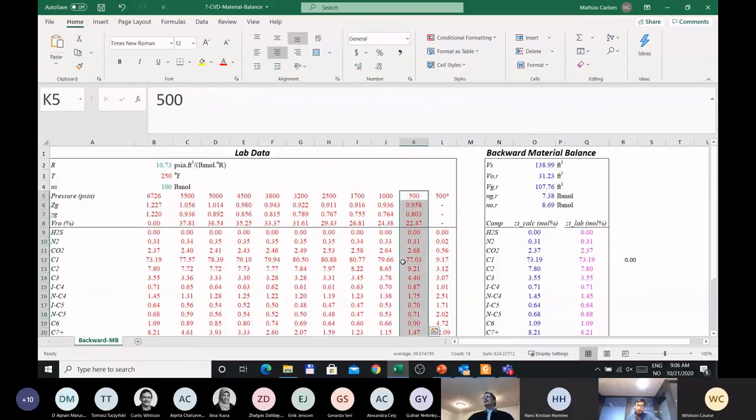Yeah. So you see that here when we are doing the material balance, we have this R, which represents the residual oil or the residual gas, and that's at the abandonment pressure, which is 500 psi, which is the last pressure in the CVD experiment. We have two phases: an equilibrium gas phase and an equilibrium oil phase.